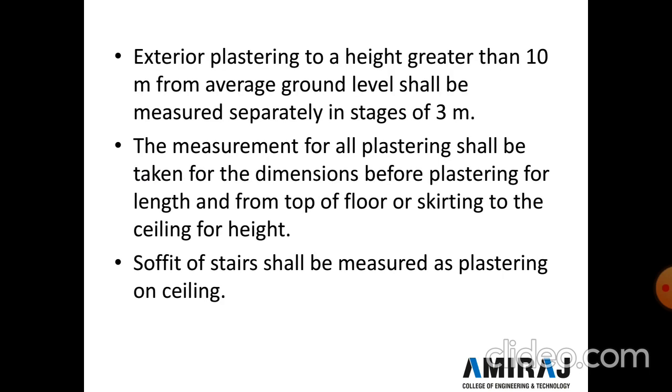Now in exterior plaster, the height greater than 10 meter from the average ground level shall be measured separately in stages of 3 meter. The measurement of all the plaster shall be taken for the dimension before plastering for the length, and from the top of floor or skirting to the ceiling for the height. Soffit of stair shall be measured as plastering on a ceiling.